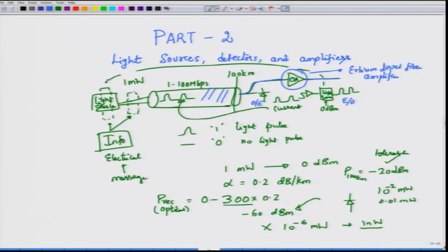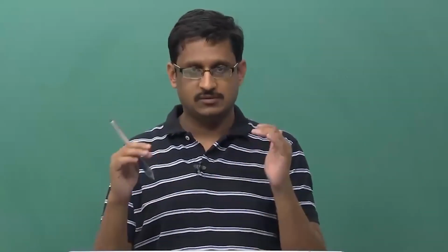Okay. So, this has a trade off, of course, since you are putting it through an optical amplifier, the optical amplifier does not give you a free lunch because it adds noise of its own. So, if you go over say 10 or 20 spans and each optical amplifier adds some amount of noise, then the final signal that you would get would be substantially noisy. However, if you follow the older approach of O to E and E to O conversion at every span, then you could clean up the noise at every span. So, therefore, there is very little noise at the end of the fiber link if you follow the old approach.